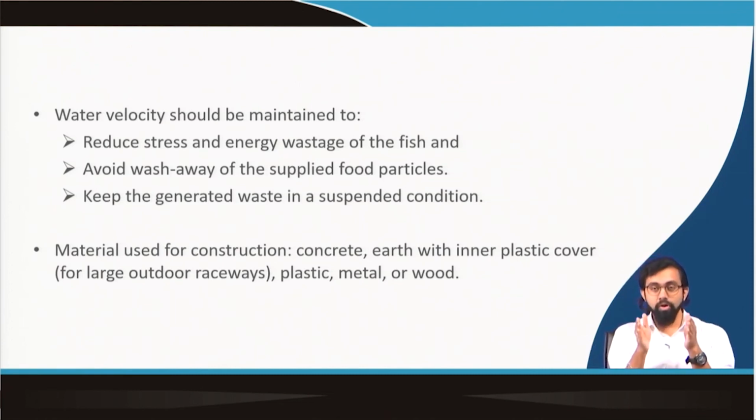But if it is a small raceway with a very small length, up to a certain limit, the water velocity can be maintained to attain the self cleaning velocity. In this way we can attain the self cleaning nature of the raceway, and the waste can be well managed at the end of the system.